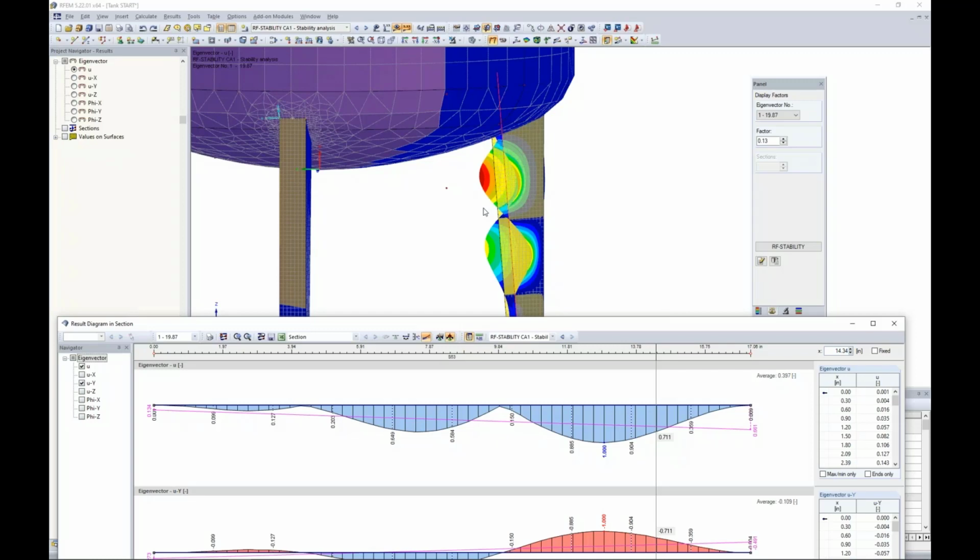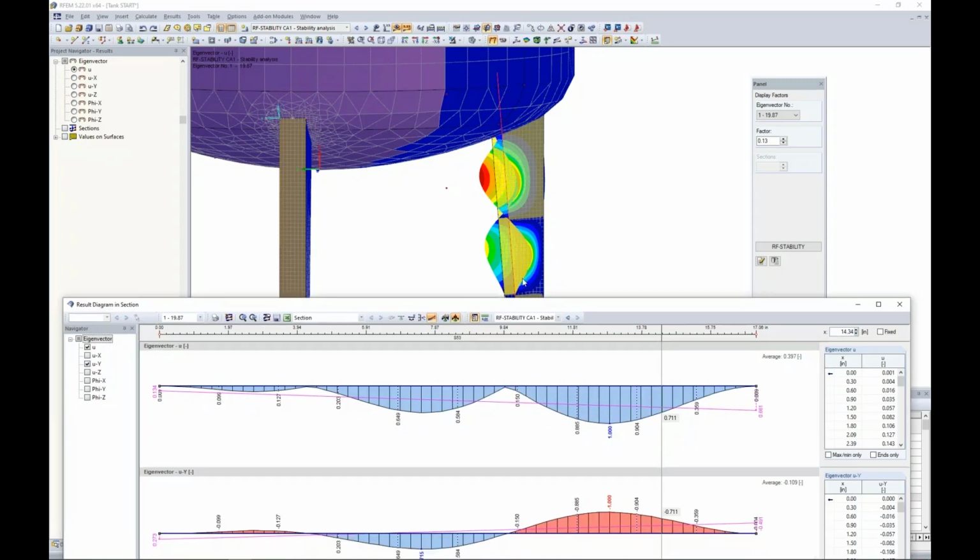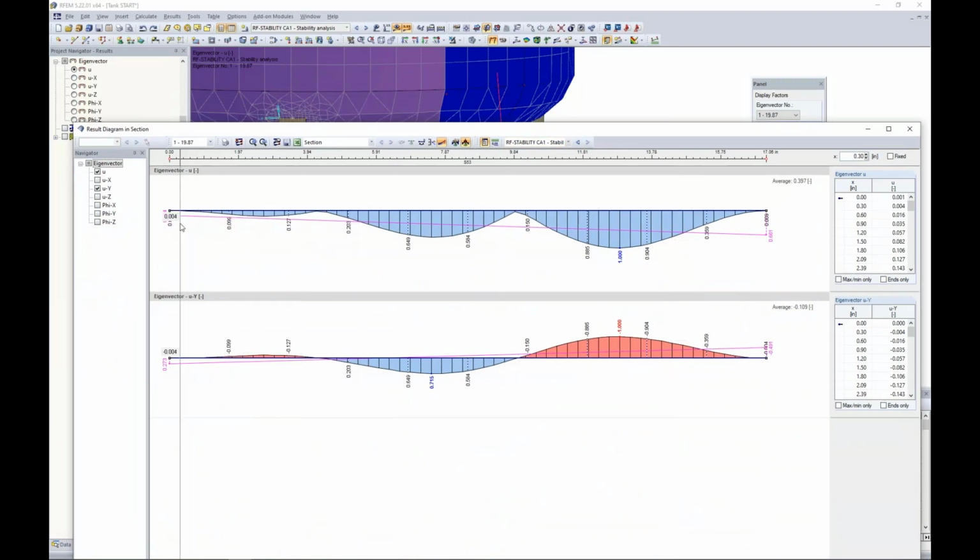Keep in mind that L is not the distance between the start of my surface and the end of my surface, but rather I want to use my working points, where I see my inflection points. Looking at the general buckling view here, the first inflection point takes place at about 10 inches, and then I scroll over to the end at 17 inches. Well, this would be my working point distance at about 7 inches in total.